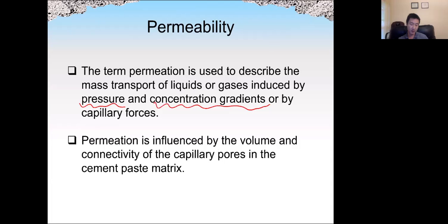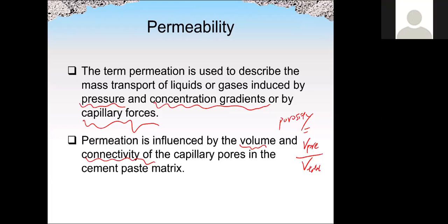And also by capillary force, the suction of the capillary force. Permeation is affected by the volume as well as the connectivity of the capillary pores. The volume of the capillary pores is quantified by the porosity, which is defined as the volume of the pores divided by the volume of the total material. So that's one thing.